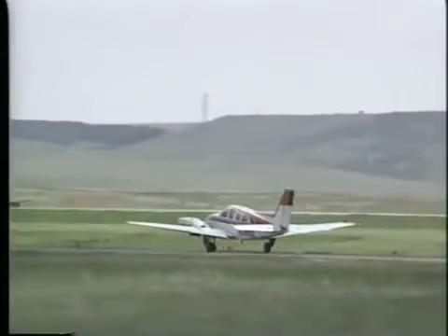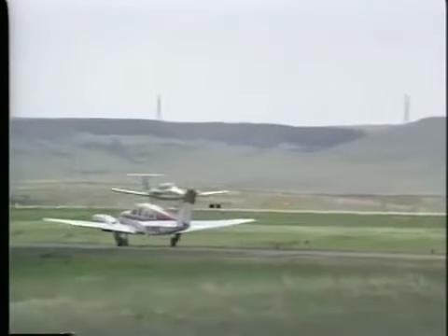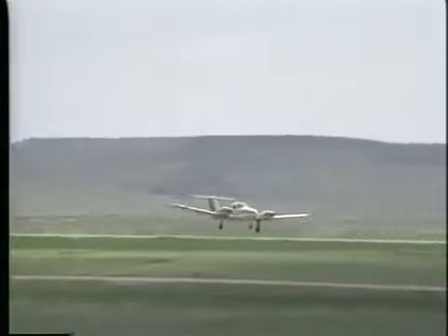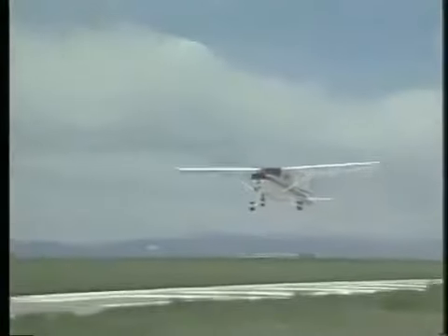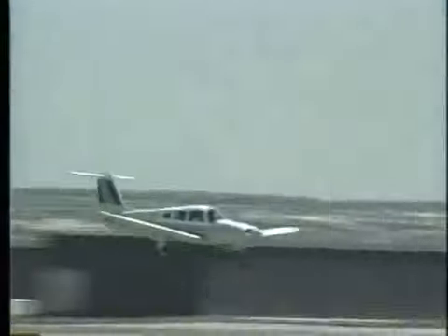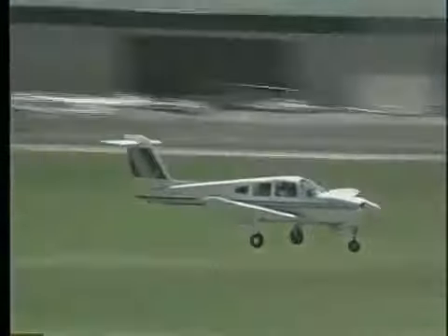Each airplane is designed to be operated at or below specified maximum weights and within a certain center of gravity range. As you learned earlier in the stability section, improper loading can adversely affect performance. In addition, all figures in the performance section of the POH are based on an airplane being loaded within the specified limits.